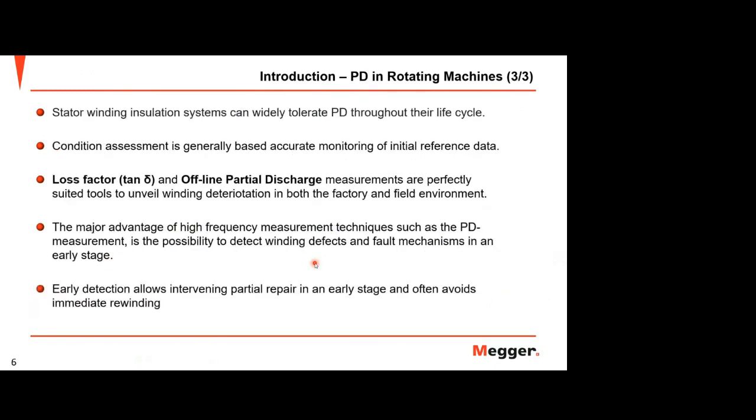At the end, the condition assessment of stator winding is not a matter of detecting partial discharge, because they are already inherent, but accurate monitoring of the development from the initial reference data, while focusing on the speed of deterioration and the development of additional discharge sites. Like loss factor, or we call it tan delta measurement,